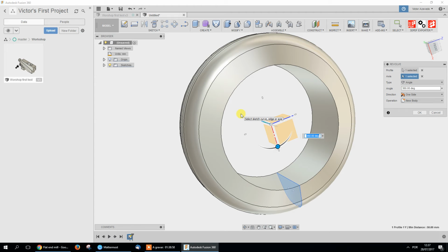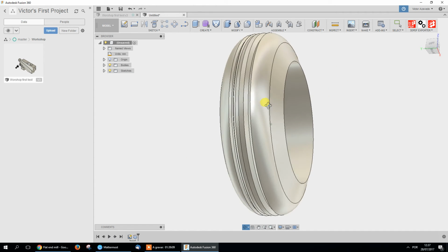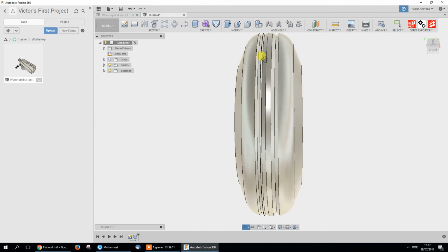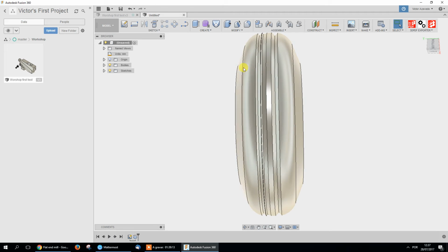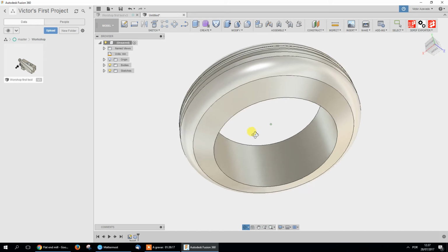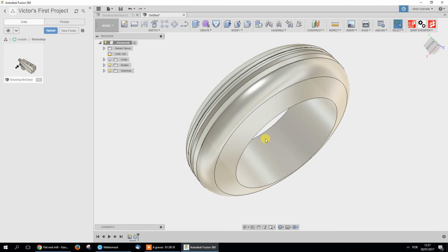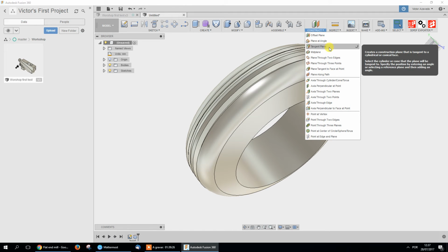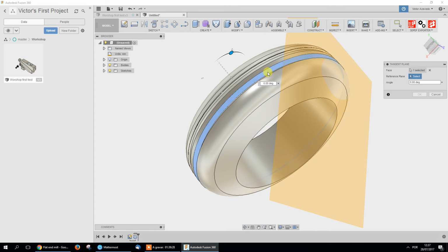So instead of using the axis of the same design or the sketch, you can use others to create a different profile. There's also ways of creating transversal profiles. It's a little bit harder because you need to embed your sketch, but you come here, tangent plane to this surface.